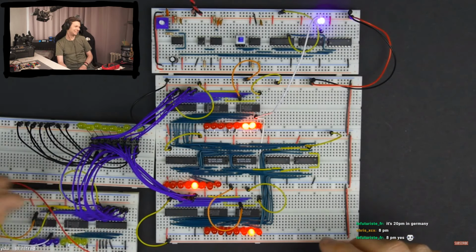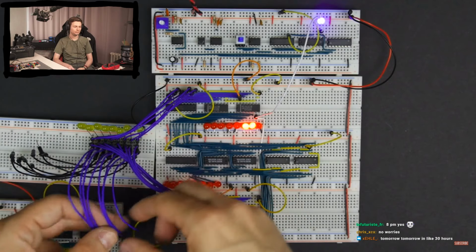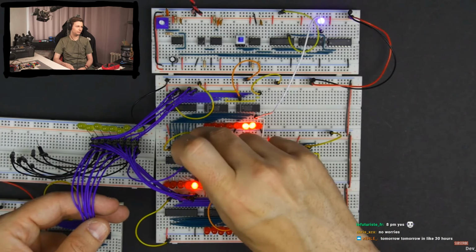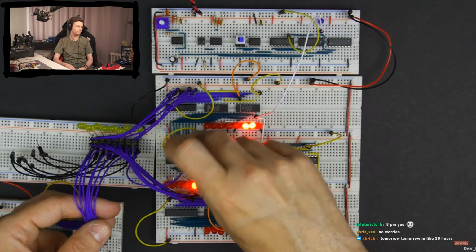So what I'm going to do is first disconnect my bus from any kind of external input here, and then I'm going to disconnect the instruction register. We're not using that right now. So rather than adding more mess to this, I'll just disconnect it and use these same wires. Being careful to keep this stuff in order, I'll hook up all 8 bits here. We did that too, by the way. And so now our bus is connected to the ALU.